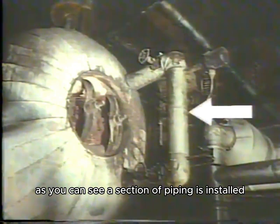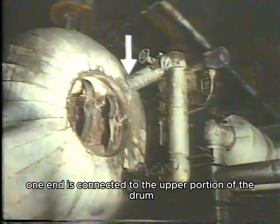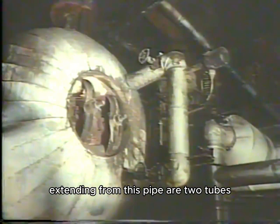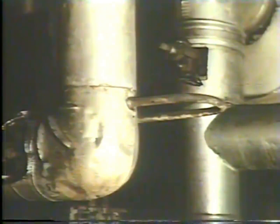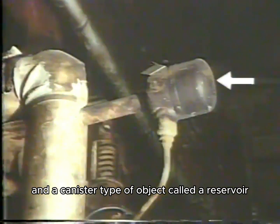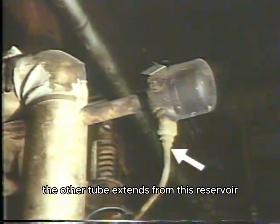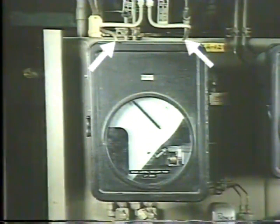As you can see, a section of piping is installed near the end of the boiler drum. One end is connected to the upper portion of the drum, and the other end is connected to the lower portion of the drum. Extending from this pipe are two tubes. One tube comes out of the lower end of the pipe, and a canister type of object called a reservoir is attached to the upper end of the pipe. The other tube extends from this reservoir. Both tubes are connected to a level transmitter.